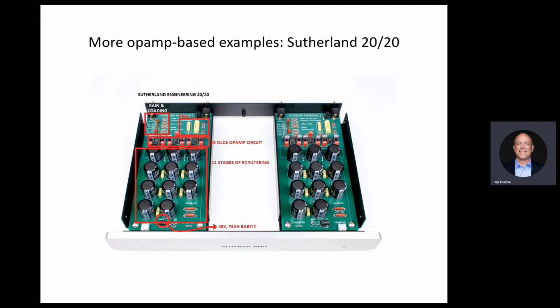And we looked at that RC, the tube guy, right? That put a lot of, well, this is the same concept. And the cost of doing extremely high rectification or stabilization is you're paying with voltage because you're going through resistors. And each one of them drops a little bit of the supply voltage. So you start with 48, you end up, I believe, with 24 volts. So you're dropping essentially half your power on this circuit.